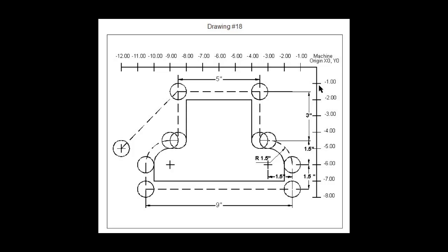Many of you probably remember growing up and you'd get a tablet or a piece of paper with a bunch of dots on it, and your job as the kid was to connect the dots and make whatever picture. Well, I think of CNC programming as being very similar to that, particularly when you're manually programming, because what you do when you're laying out your program is you actually create the individual tool locations, much like the dot on those pictures, and you put your tool locations all around the drawing.